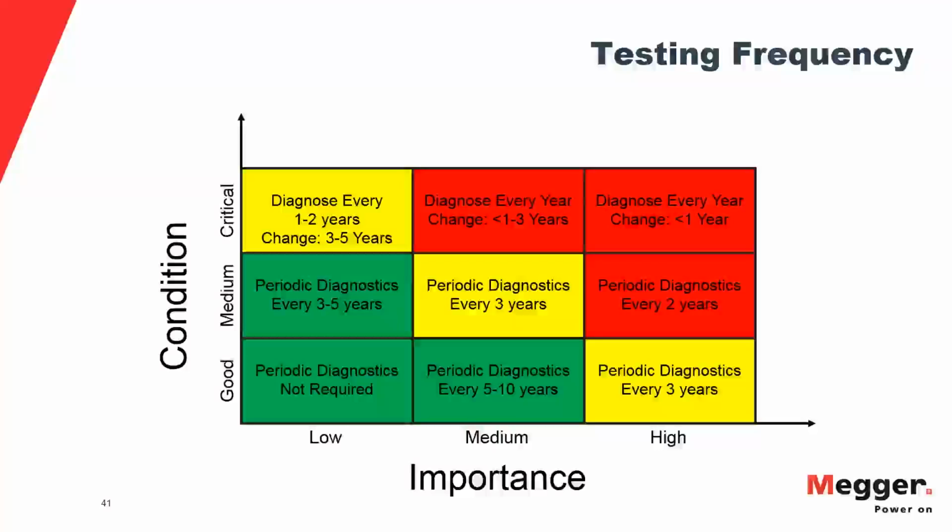When you do it online or with handheld in the substation for switchgear and so forth, you typically have the choice between several different sensors feeding into the system. So you have UHF, and then you have also radio frequency antennas for certain applications. When you do your frequency sweep there to find sources, you're doing this in the different bands. For offline testing, you pretty much integrate the whole signal from the low kilohertz to the high megahertz, and that gives you the apparent charge that you are actually getting. And of course, if there is an interference in these frequency bands, then you will see this. But for sure, not audio frequencies like our ear hears, that's typically too low.